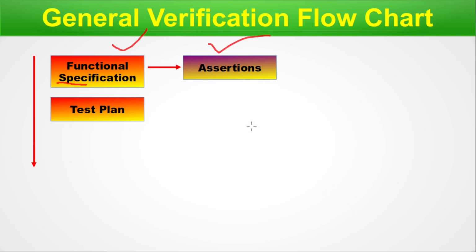Once you go into the detail of the coding, you will understand what assertions are. But overall, I can say assertions are a way of hard coding the way a particular block or section of code, which corresponds to our design behavior, should remain firm, and in case there is a violation, the verification tool should flag an error or warning, whatever is applicable.